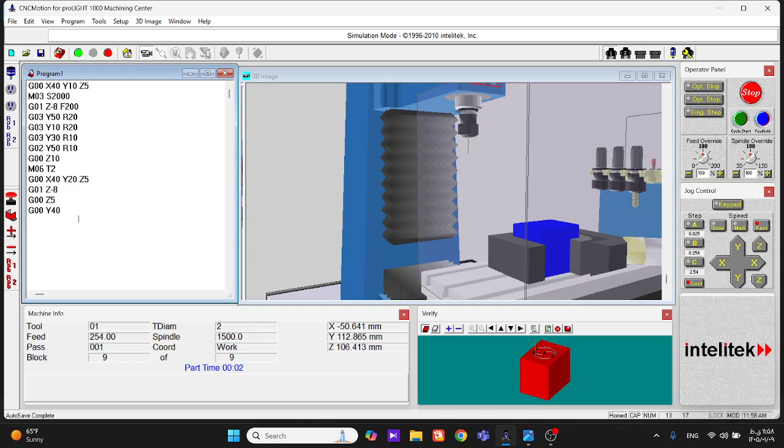So when I'm on the top of the second position and I want to make a deep hole, again I will make the G01, the linear interpolation, with the depth, again deducted by Z, it will be -8. It means 8 millimeters goes down into the specimen, the depth on the specimen.